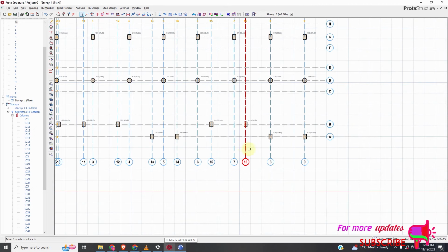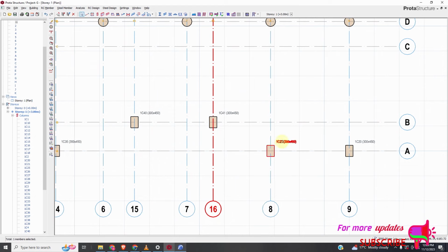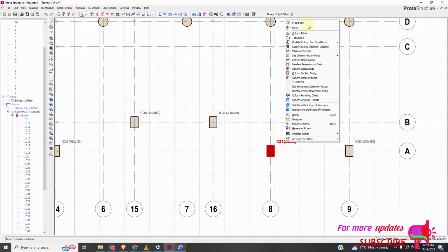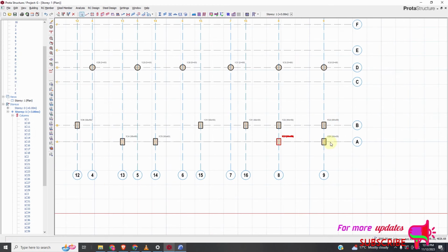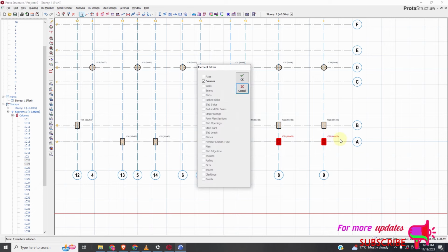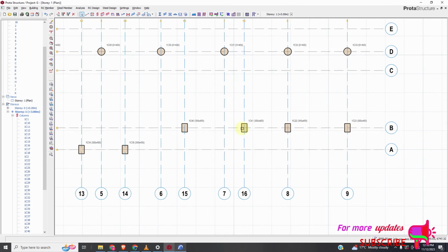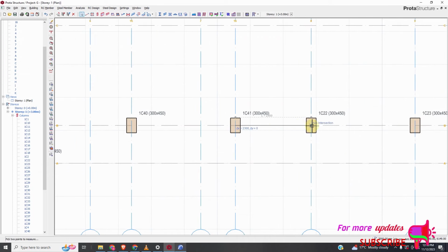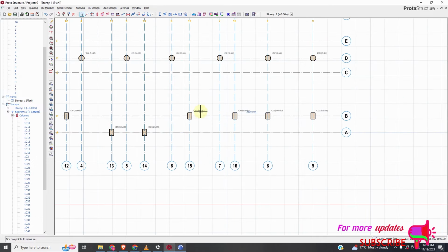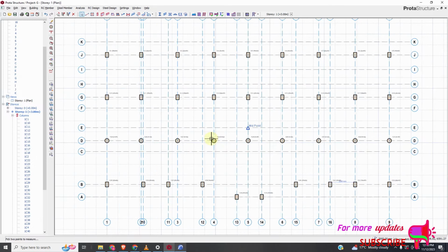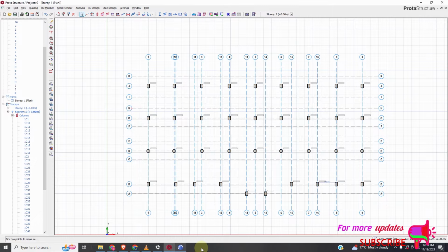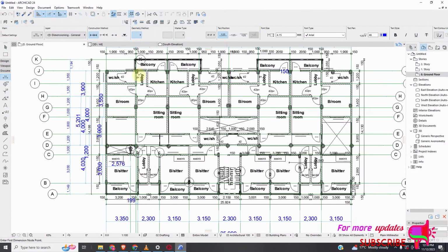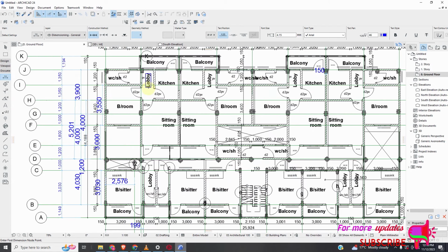So actually, I think this should be just here. So just copy this property and then go it there and then there. I just need to delete this. So just confirm that our distance is from 300. So just right click, measure from here. Like it's 2300, you can see. So from here we can maybe add our beams. Before we add these, there are beams here also. So we just offset these ones.